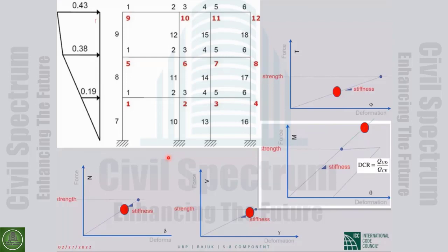when we look at the procedure for the evaluation of the building, for systematic evaluation with linear analysis, we have to estimate the demands. So give us the response spectrum for the earthquake that you want, the earthquake with the return period that you want.